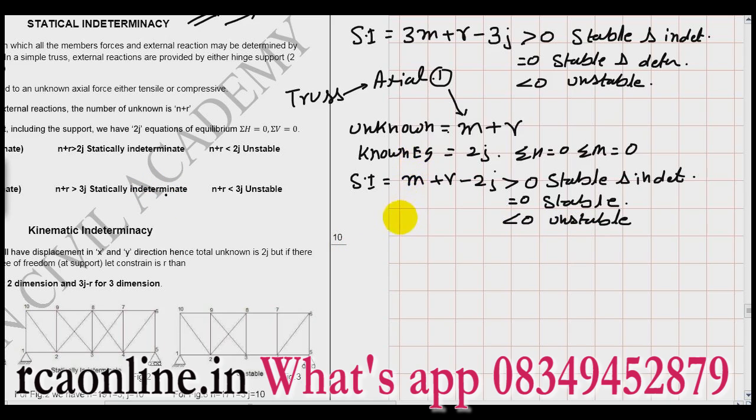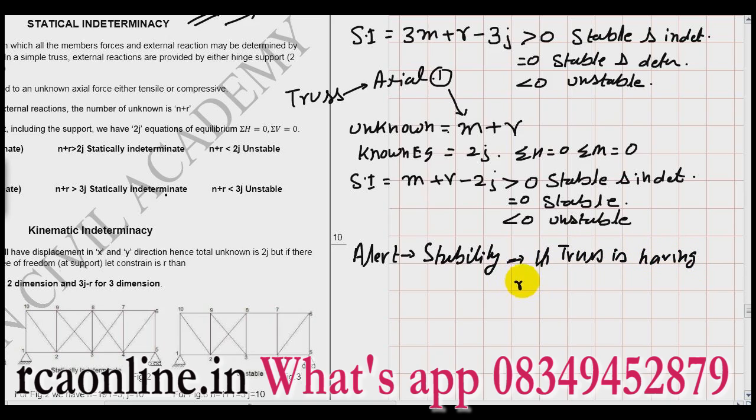The other part in this is to understand the stability. Other than the equation, you have to be alert for the stability, which I discussed in my first video of the truss analysis, that if a truss is having a rectangular part, then it will be unstable.